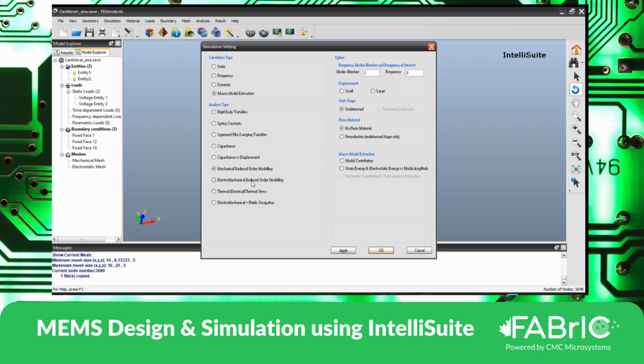Okay, so similarly, we can perform electromechanical reduced order model, where we see the modal contribution, the strain energy associated with each mode of vibration. Once these two things are done, we do the mutual capacitance and complete the simulation part of it. And the benefit of running the reduced order model simulation is that we can use the same ROM file to perform dynamic analysis.